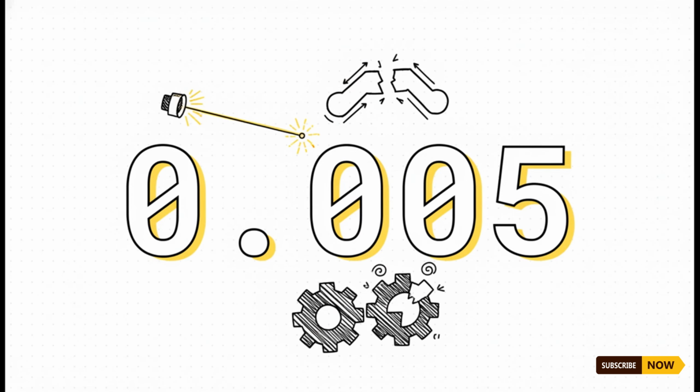Now, what's really interesting is the sheer scale of this number. A typical laser kerf is between 0.002 and 0.005 of an inch. To a novice walking into the shop for the first time, that decimal seems microscopic. It's so tiny that it's incredibly tempting to just ignore it entirely and assume the machine will sort it out. But let me tell you, from bitter, frustrating experience, you cannot negotiate with physics. If you ignore a 0.005 of an inch gap on a precision part, that tiny width of a laser beam will completely ruin the interlocking joints or press fits of your final assembly.